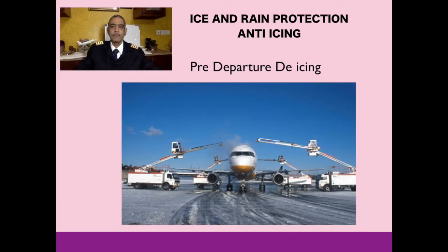And important to cover this, in almost all airports which are prone to heavy snowfall and aircraft icing, we have something called airframe de-icing before takeoff. You will appreciate that it's very critical for the aircraft not to take off with icing formed over the airframe, because it alters the airflow characteristics and it can be detrimental.